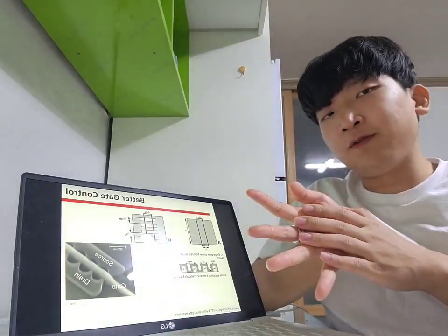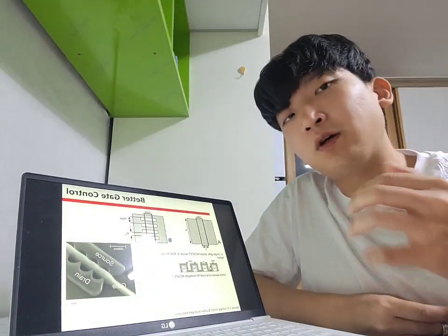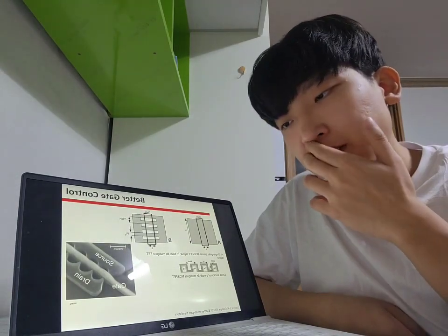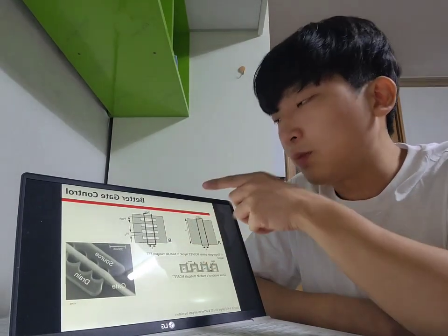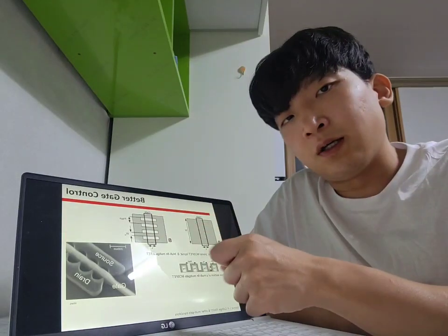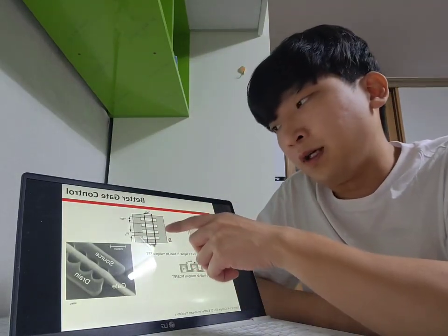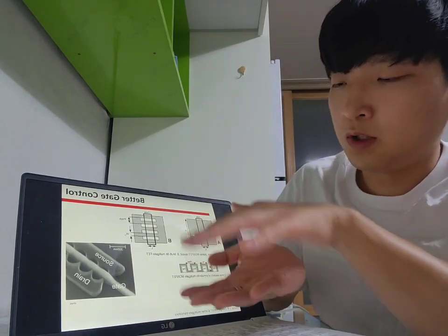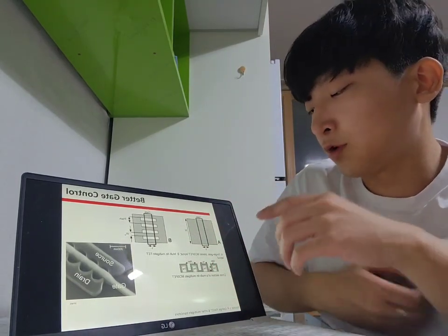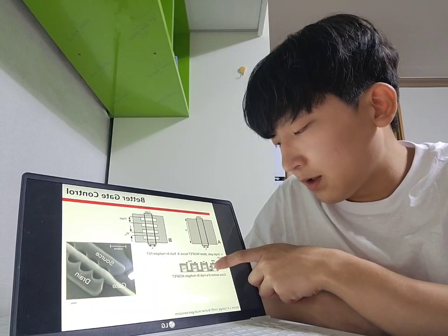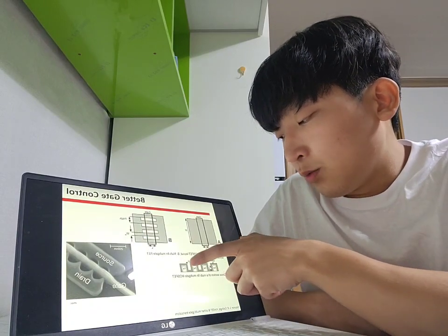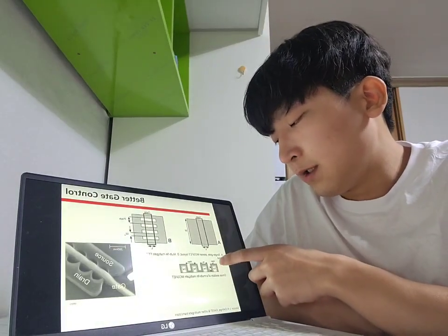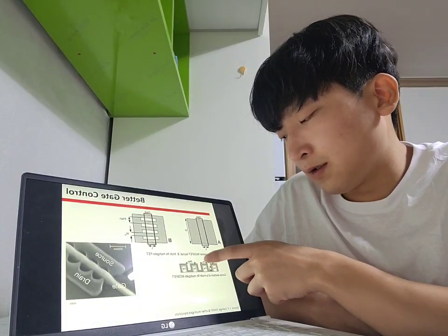Why we should use FinFET is because we can get better control of the channel with the gate. Because as we can see in this picture, you might think the width gets lower, but as this is 3D, and we looked at it as a cross-section view, we have some width, but the total width includes the height of the gate.